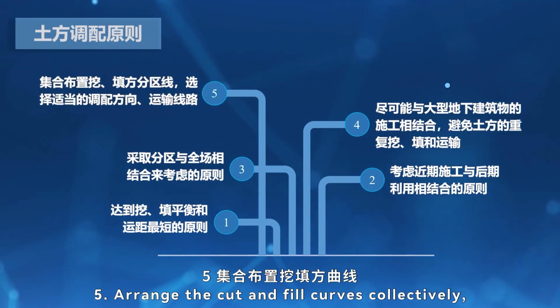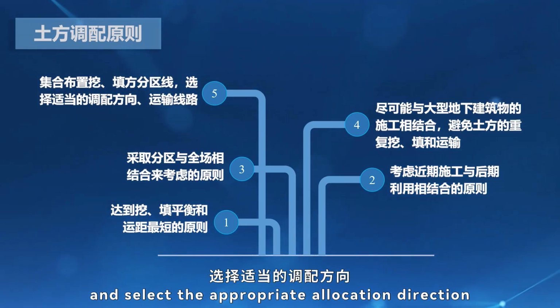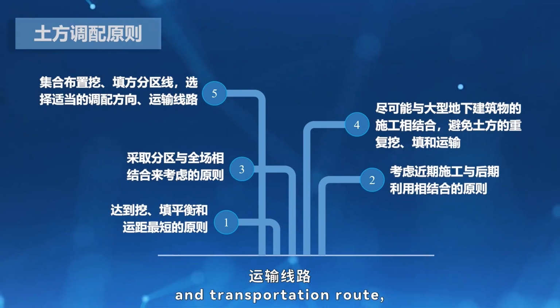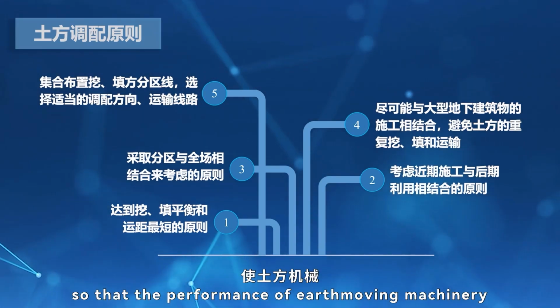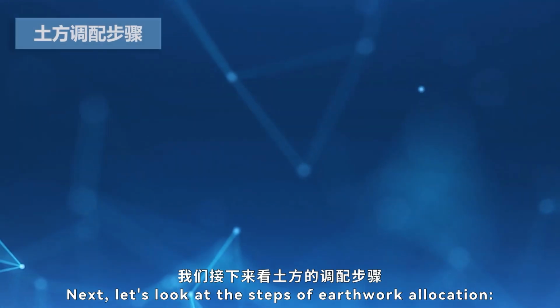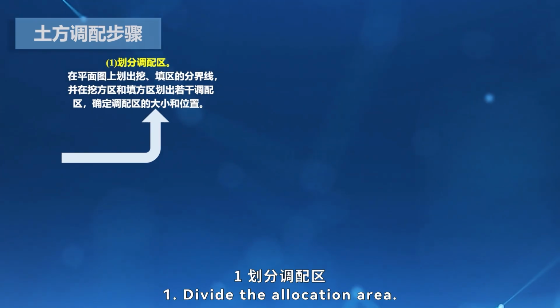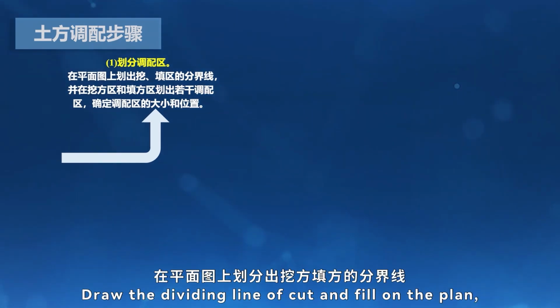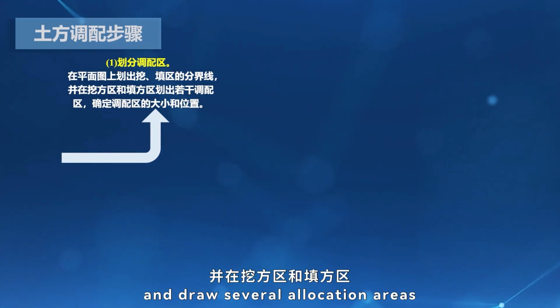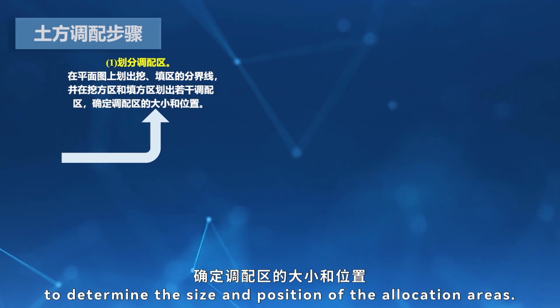5. Arrange the cut and fill curves collectively, and select the appropriate allocation direction and transportation route so that the performance of earth-moving machinery and transportation vehicles can be fully exerted. Next, let's look at the steps of earthwork allocation. 1. Divide the allocation area. Draw the dividing line of cut and fill on the plan, and draw several allocation areas in the cut area and fill area to determine the size and the position of the allocation areas.